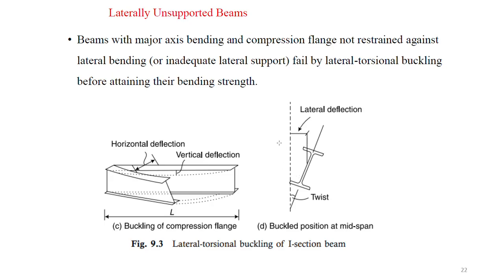Initially it will be vertical, this position will be here, this beam will be situated here, but after application of the load, this particular beam has been rotated in this direction, and it has deflected. The top compression portion of this beam has been deflected away from its vertical axis, okay. This type of deflection we call the lateral deflection of the beams, and this type of support we call a laterally unsupported beam.